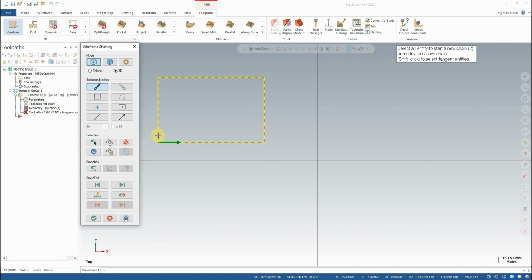The difference being conventional milling, where you're catching the material on the back edge of the tool every time you come in for a cut, inherently pulling the cutter into the material instead of pushing away from the material. For these reasons, climb milling is generally preferred for most applications, so try to always be sure that your arrows are traveling in the right direction.